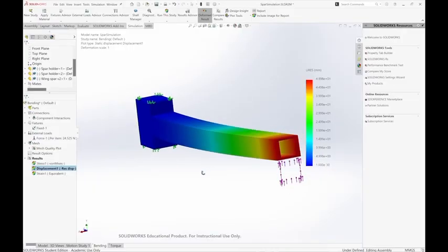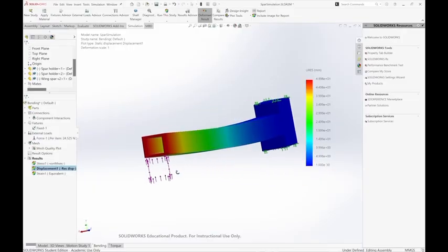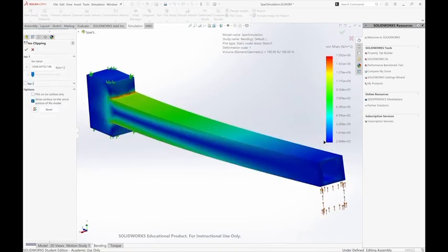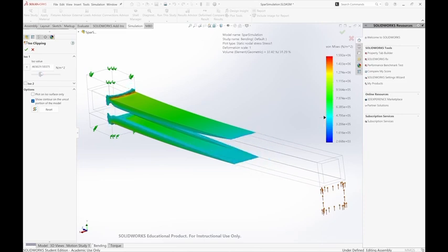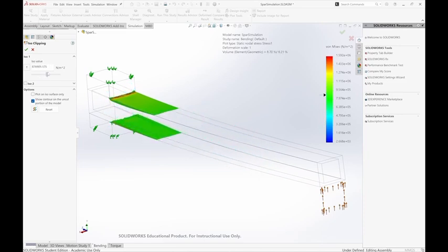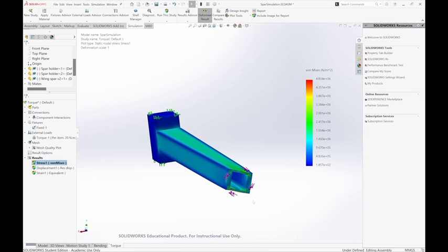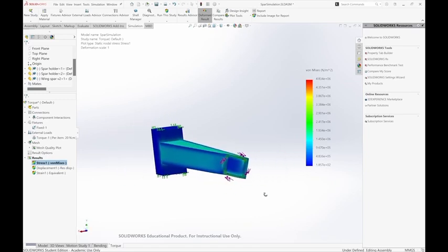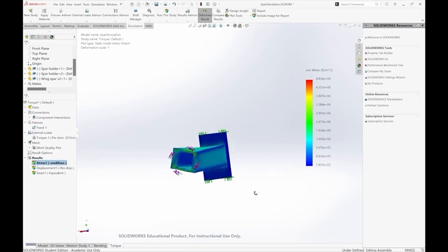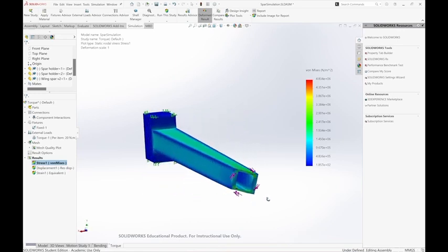After designing using the spreadsheet, we use SolidWorks to simulate the behaviors of the spar under load. Under 2.5 kilograms, about 24.5 Newtons of load on the wingtip, the results show that the stress is mainly located near the root and the tip is not affected. With 30 Newton-meters of torque on the wingtip, the top and bottom surfaces experience more stress than the sides, as you can tell by the differences in the color of the model.